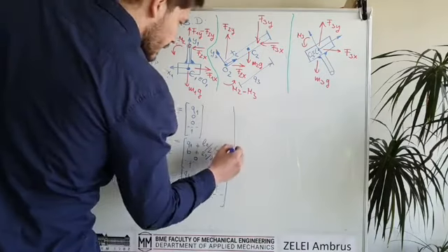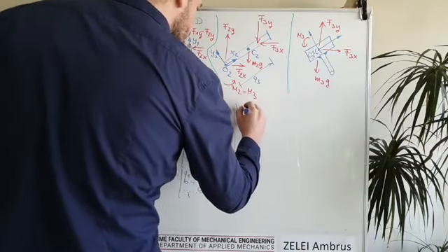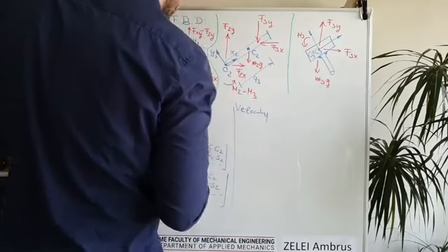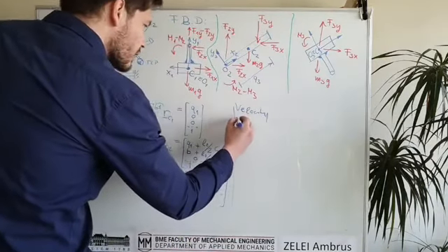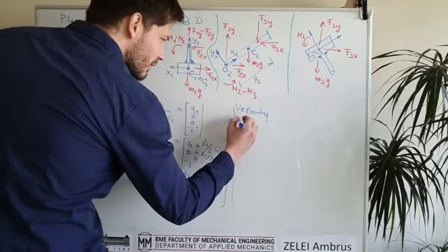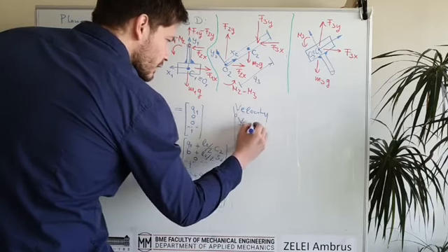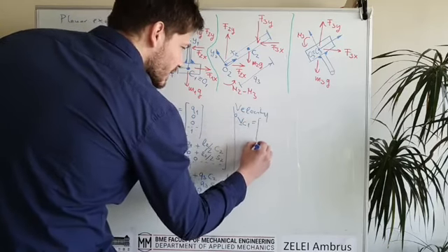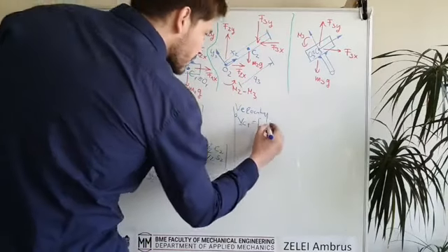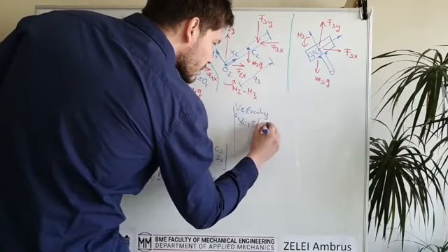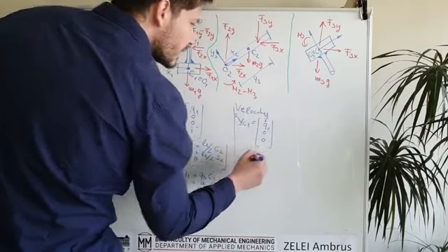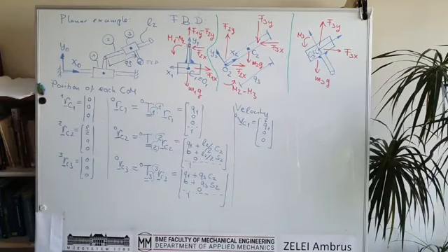And then we have to calculate the velocity for each center of mass. I will just show how to do it. Now we can simply time differentiate everything. So the center of mass velocity for the first rigid body is simply Q1 dot, 0, 0. Now we can get rid of the homogeneous form.